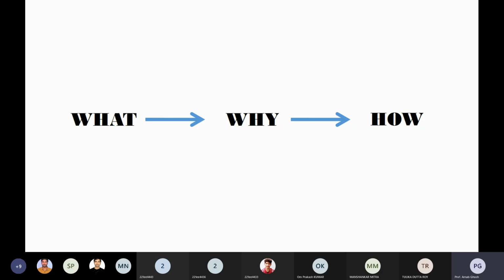What type of switch you are using matters. You designed for 5 volts, you can use a switch rated for a maximum of 50 volts, but if any spike comes beyond 50, your switch will be damaged. So you have to design everything as per your rating and your specifications. That's the thing. How they are related, I will discuss one by one.